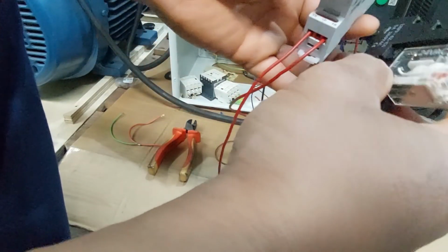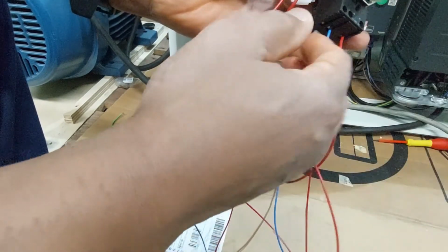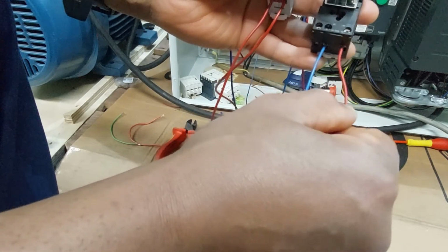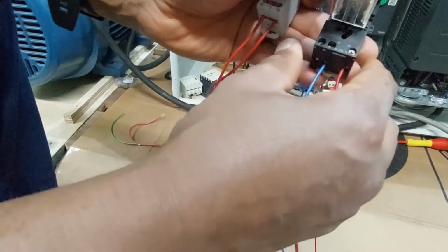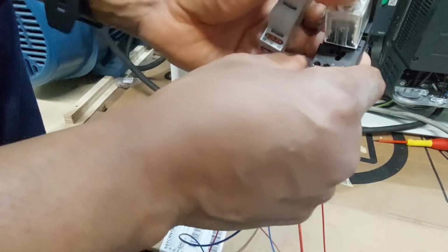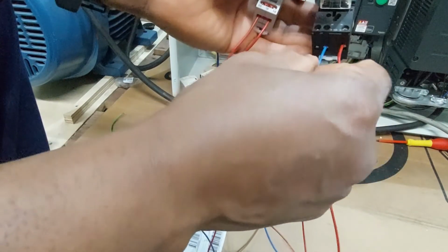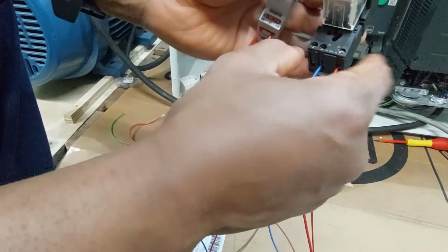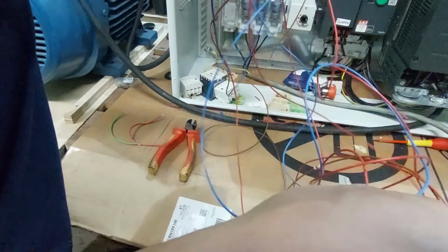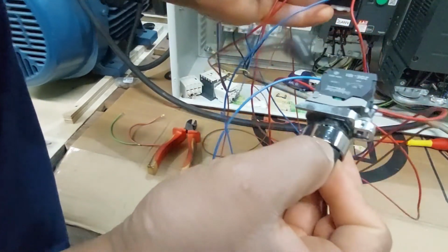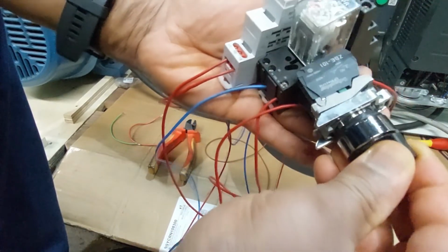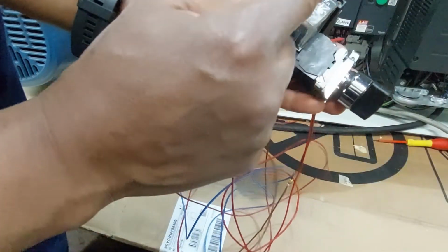So what it's going to do is that it's going to be supplying positive, supplying phase to the contact, supplying phase to the coil. So you can put AC or DC here, depending on what you want to use it for. So when it switches, it will close, and this will activate. So how I've used it: when I supply voltage to the timer, the timer will begin to count the time, and I put it for like 30 seconds. So after 30 seconds, it's going to switch this one on.